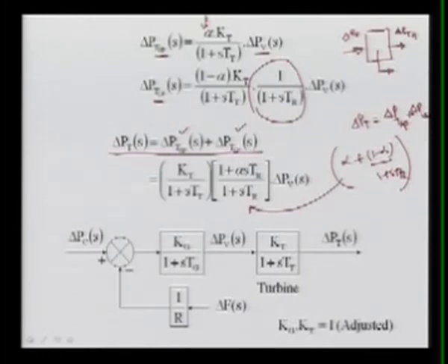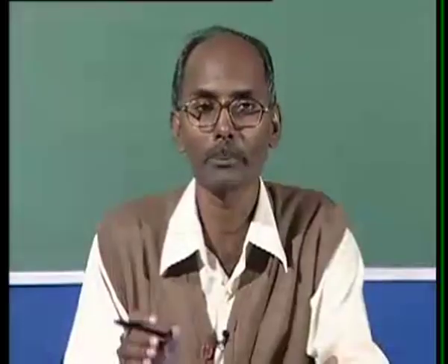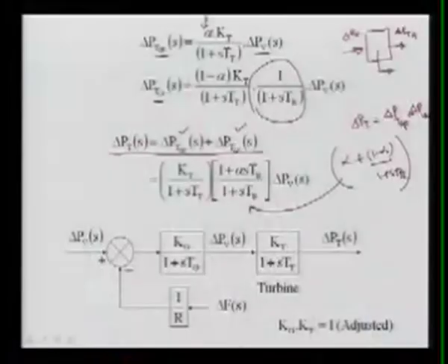So you can see we are getting a complex transfer function of the complete turbine which has the reheating facility. For simplicity, let us take it as not having the reheating facility. So we have to ignore this, putting alpha equal to unity, which means only the HP part is there, only the high pressure turbine. So this part will vanish.